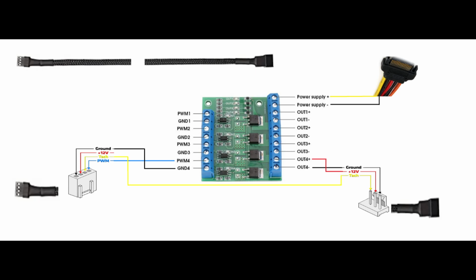Now here is where I might lose some of you. The red is only connected on the output of the module coming from the right side of the connector. The leftover wire on the left side is terminated and not used. This means cover the end of the wire with electrical tape or heat shrink. Last is the PWM wire. It is often blue. It is only connected on the left side of the module and also terminated and not used on the right side connector.